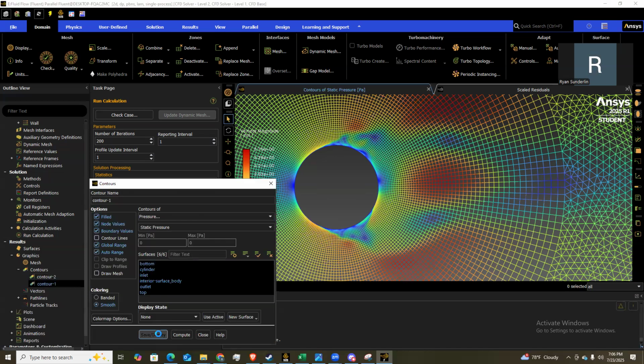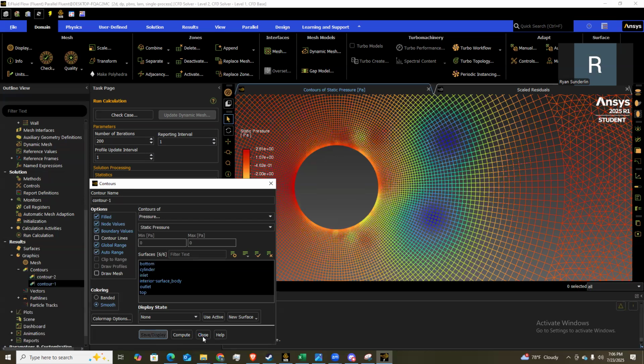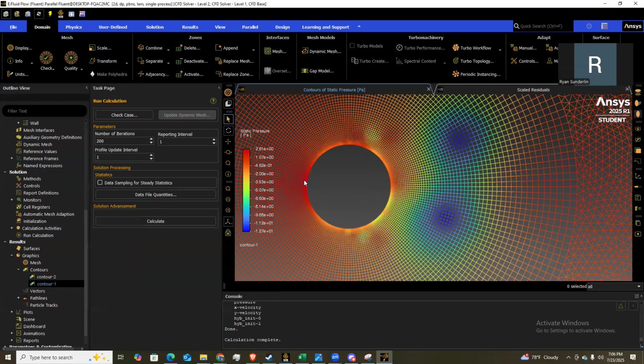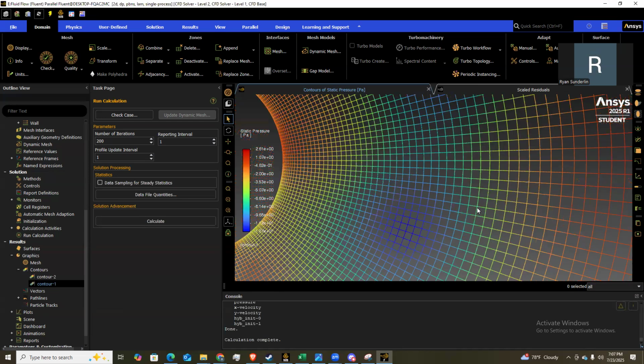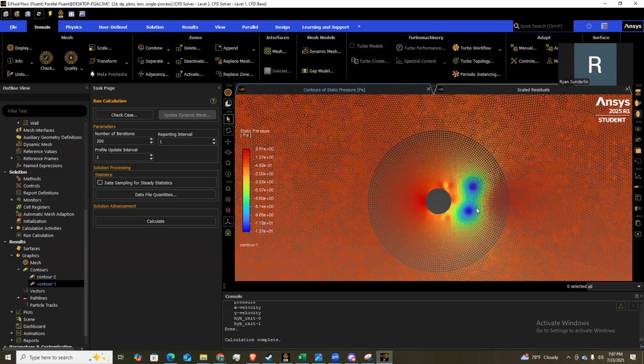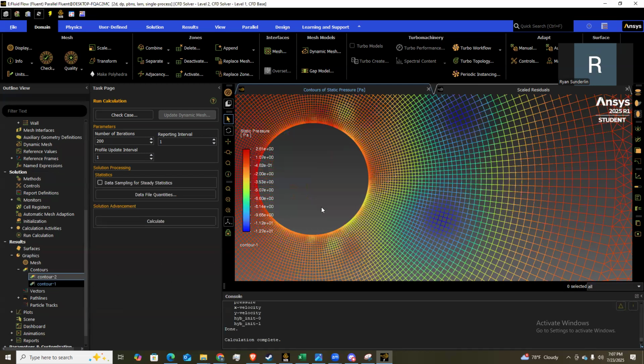And now we can do the pressure contour. And here it's the same. Velocity reaches its 0 mark right around the stagnation point, which is where the highest pressure is. And these eddies create zones of low pressure as well. Correlates pretty well to the theory. And that's pretty much it for the laminar case.